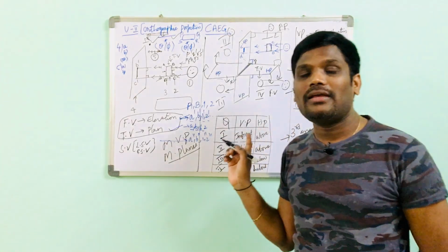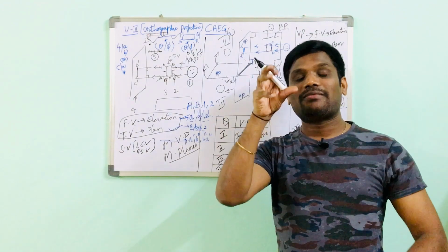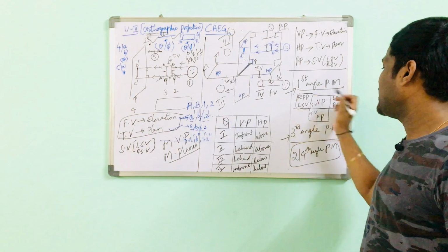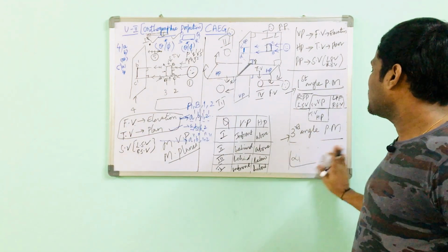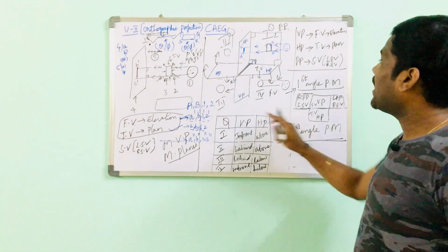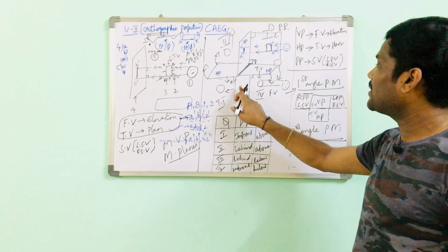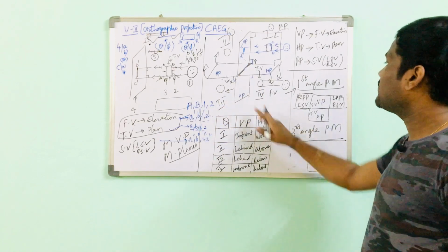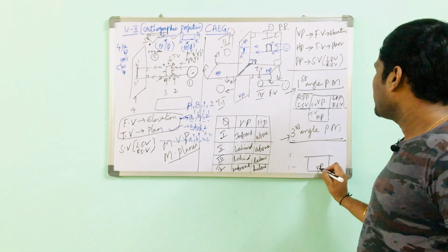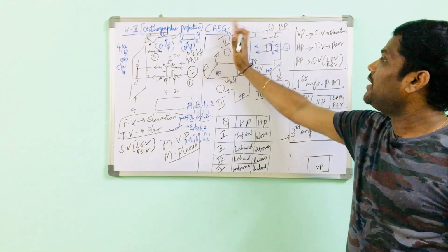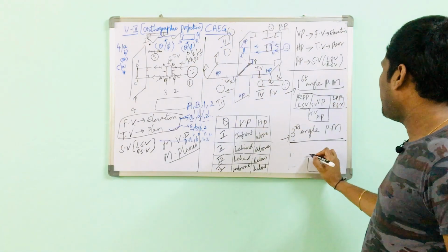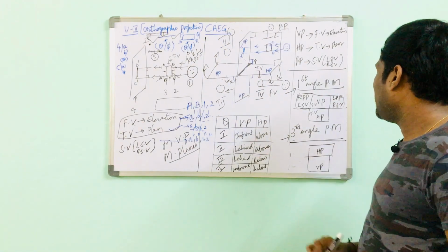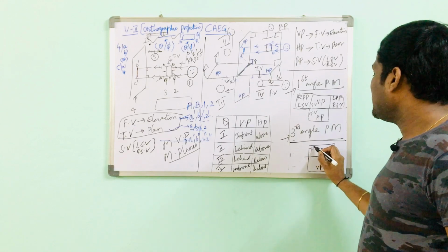I have explained this very clearly with the help of a set of planes and an object. Please go through it, or just work it out now. Now coming to the third angle projection method: where is the third angle? This is the third angle projection method. If you see here, this is the reference line, and below it, the vertical plane remains vertical, whereas the horizontal plane will be tilted 90 degrees clockwise, open. So that will be like this. So this is nothing but the horizontal plane. In the horizontal plane we'll see the top view.